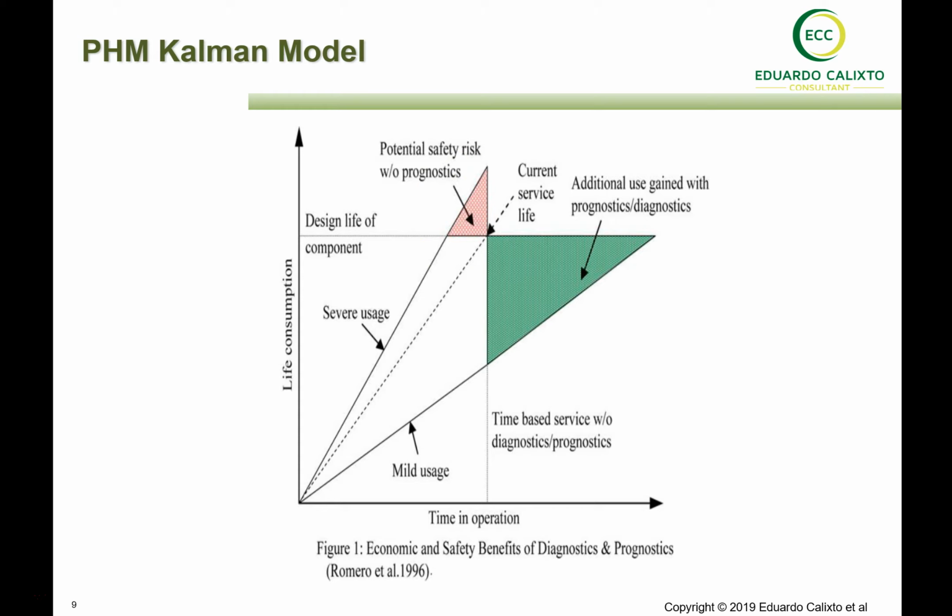So when your system has higher vibration than defined in the design for the operation of such equipment, a compressor, a pump, what's the effect on the impellers, what's the effect on other components, such as the bearings, for example, when such equipment has a high temperature sensor reading, operating over the temperature limits, and what is the remaining life prediction. And it's very important that such a model is updated online. Whenever new information comes in, the remaining life will be updated automatically.